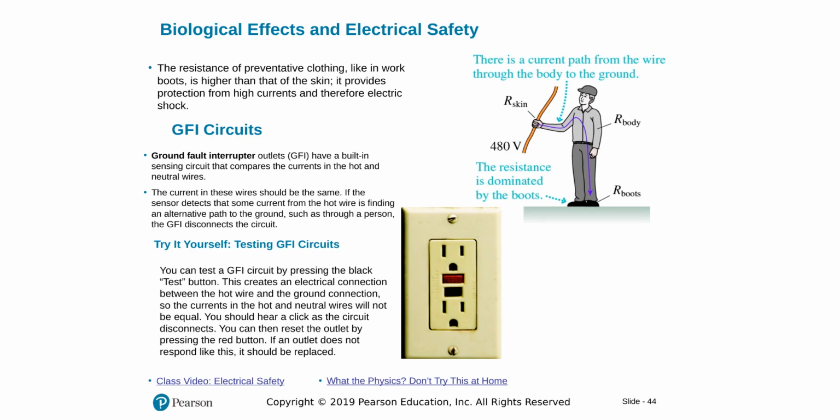To protect, we have many systems. As we talked before, we have circuit breakers. In places where it's wet, in kitchens and in bathrooms, we have what we call a ground fault interrupter. It's a system that breaks the current. If there is an outgoing current I1 and it measures an incoming current I2, it knows that the current goes out, goes to some devices, and should come back as the same current.